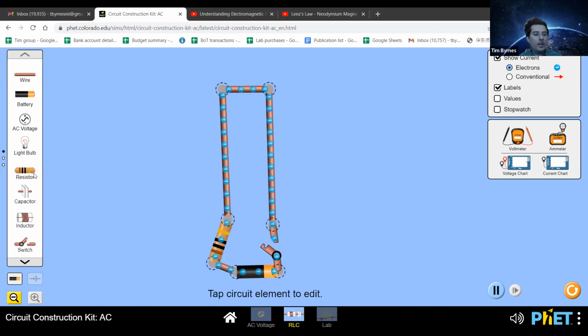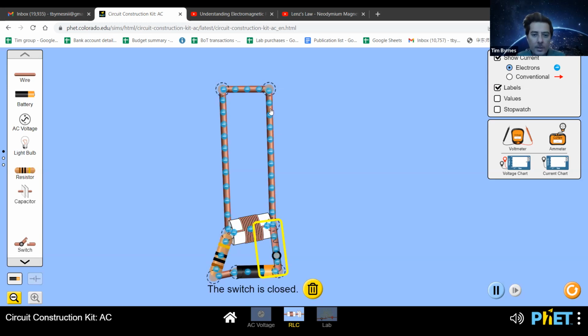So let me just put the inductor back there, and once this is... oh, okay, actually, sorry, I need to get this one flowing first. So now when I close this switch, it's going, and then I'll put that wire back. And so over here, there's a current going through the inductor. And when I open this switch, the inductor is like, no, I don't want the current to change. I want the current to just remain the same value.